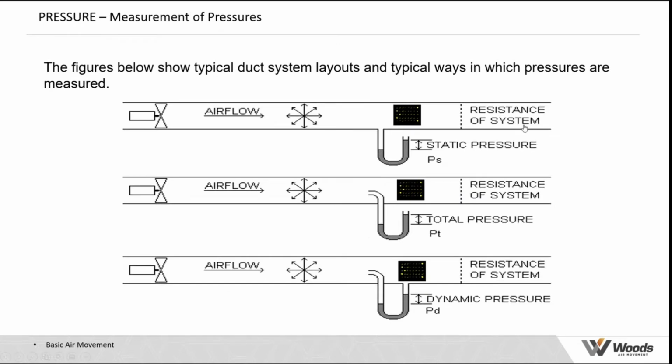So in very simple terms, there's our fan, a very nice long straight duct. It's working against this resistance here. So at this point where we want to measure the performance, remember, static pressure is equal in all directions. So if I measure that on a side tapping on the duct, measure that to atmosphere, the difference in the pressure gauge, which used to be in water gauges because you'd have a U-tube with water in it, but now of course it's done electronically, that is the static pressure.